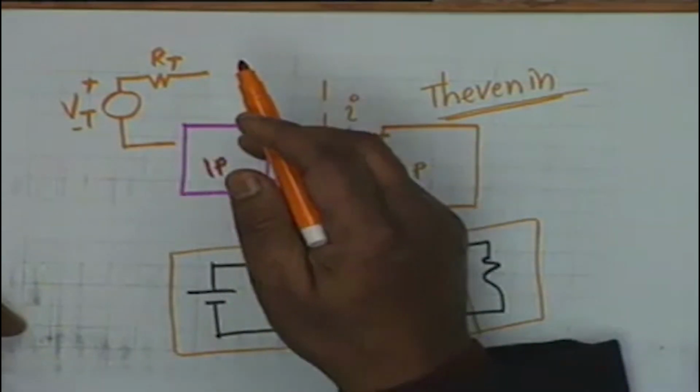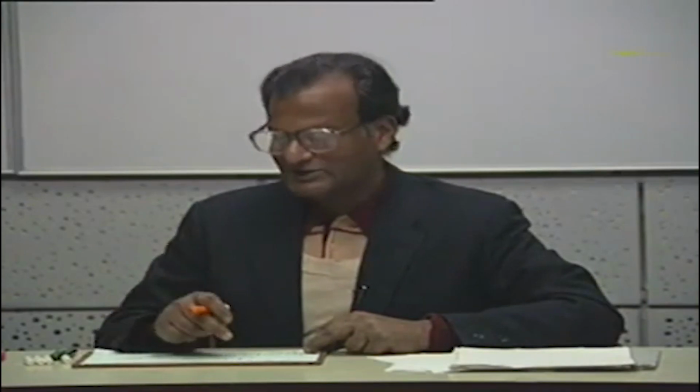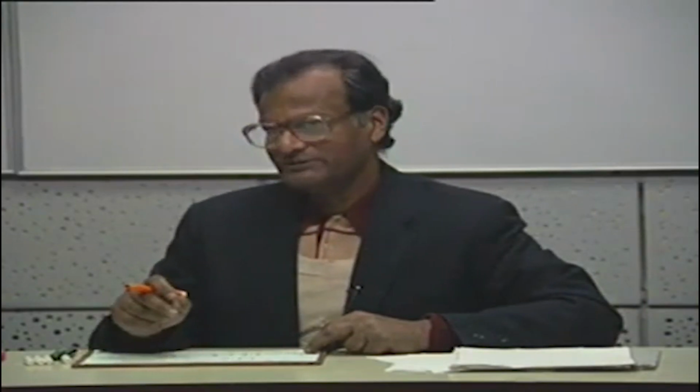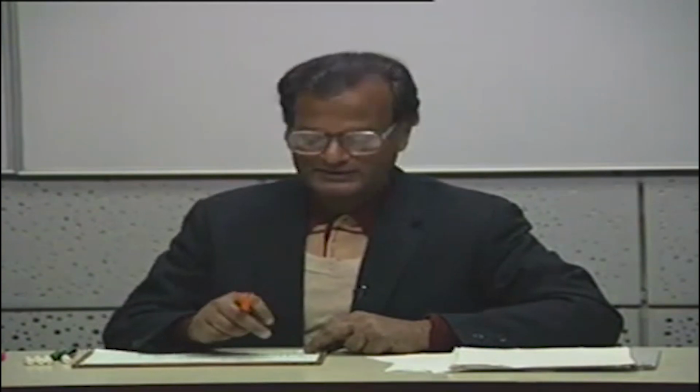Sorry, it's not an arbitrary 2-port, it's a 1-port, an arbitrary connection of a 1-port to another 1-port. In so far as the load current is concerned, the 1-port can be replaced by an equivalent voltage source in series with an equivalent resistance. The values of VT and RT we shall consider on Friday.